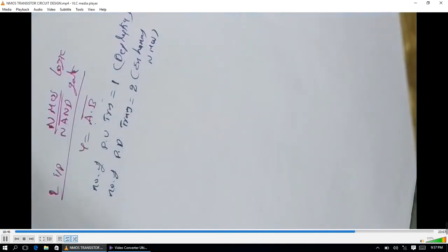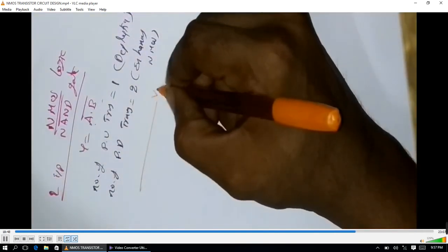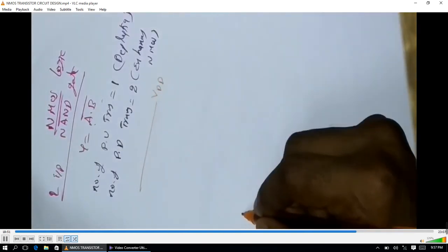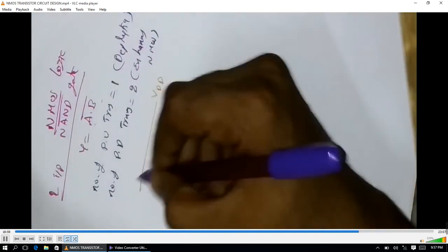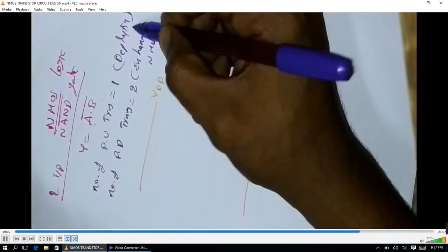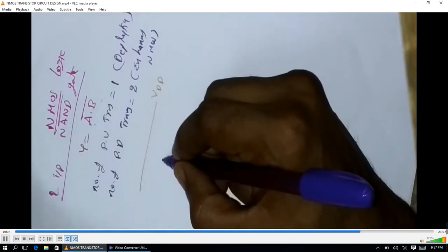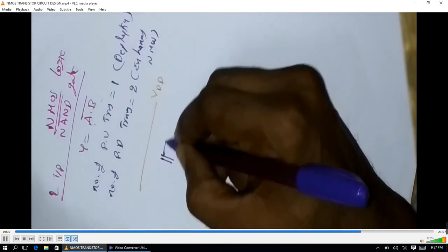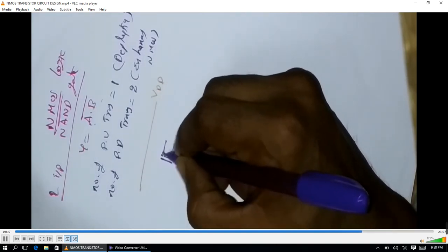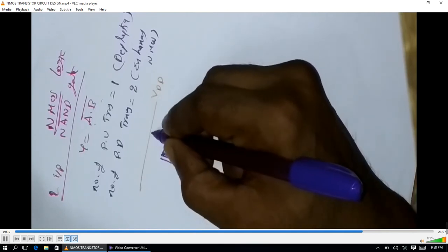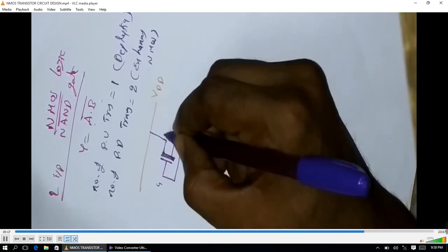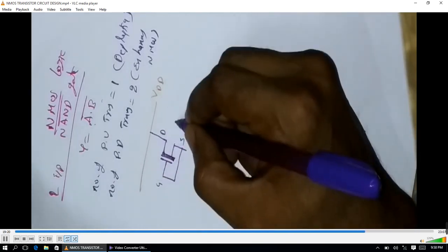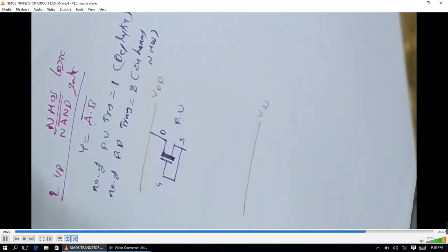Thus you can consider VDD and VSS. Okay, so further, first we can design the pull-up transistor. There should be only one, that must be a depletion mode NMOS transistor. This gate is connected to the source always, this way depletion mode NMOS for pull-up transistor.